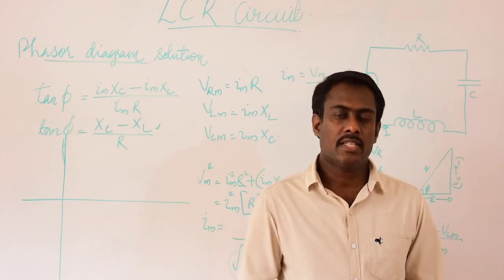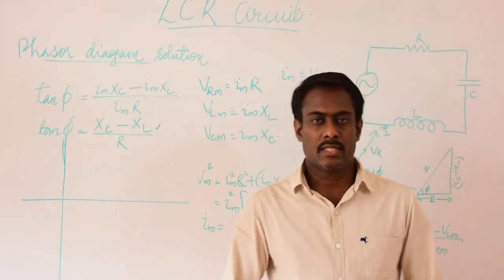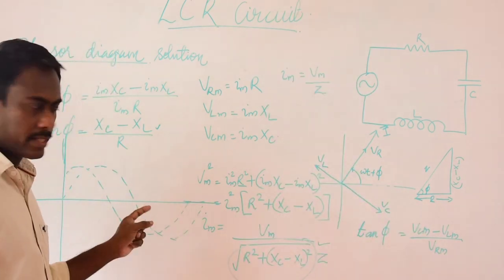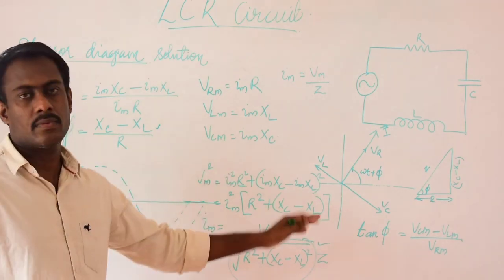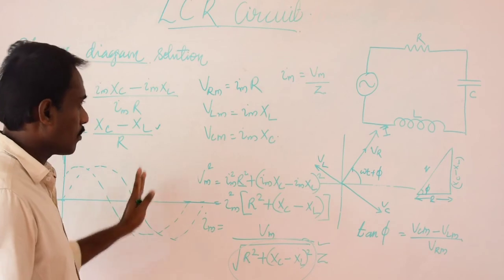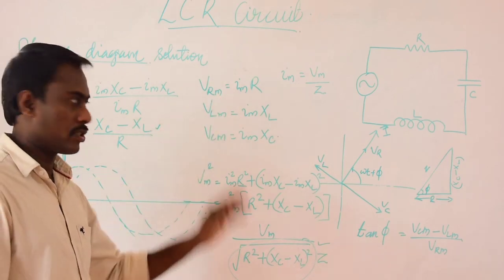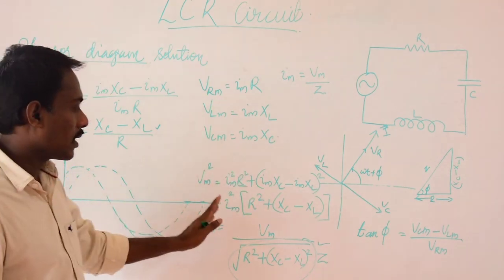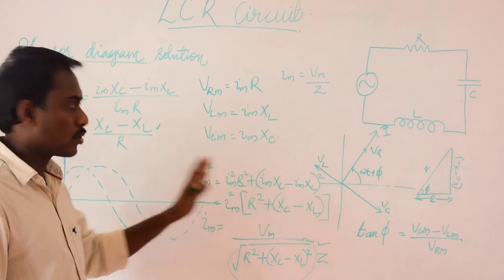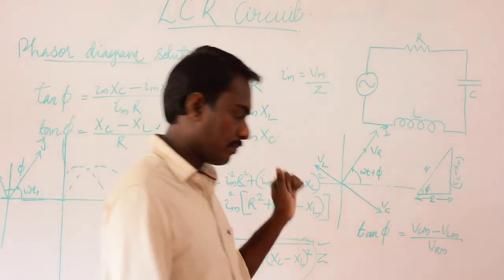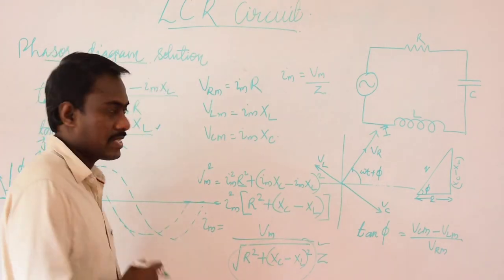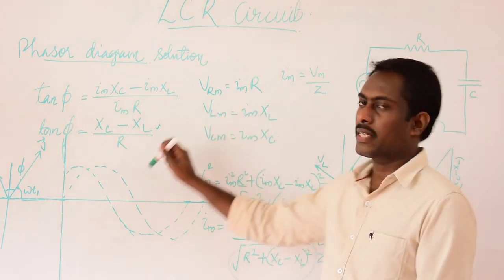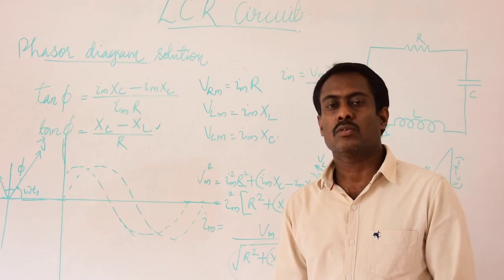Thus we have obtained a phasor and amplitude diagram for an LCR series circuit with the help of this phasor diagram. This is the graphical representation. The voltage current relation that we have resolved by the phasor diagram method has certain disadvantages. This diagram says nothing about the initial condition. Anyone can take any arbitrary time t1 and draw the different phasors to show the phase differences between them, and therefore the solution so obtained is called a steady state solution. This is not a general solution. A generalized solution can be obtained by the analytical method that we are going to see in the next session.